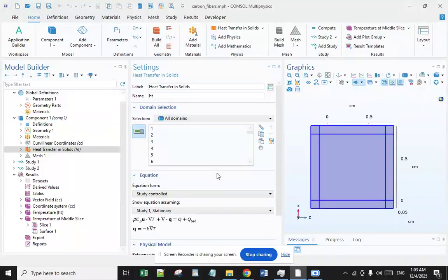Three types of nanofillers, including particle type nano zinc oxide, rod type carbon nanotubes, and flake type graphene nanoplatelets, or GNPs, are selected based on their geometrical morphologies. Their effect on the thermal conductive characteristics of WFP composites is systematically analyzed.